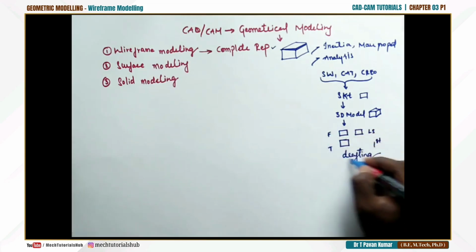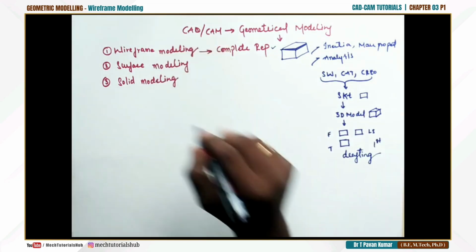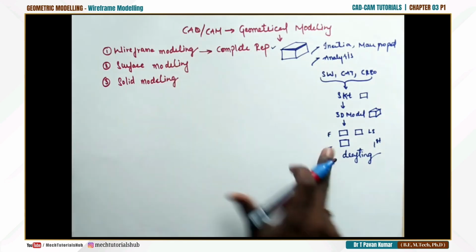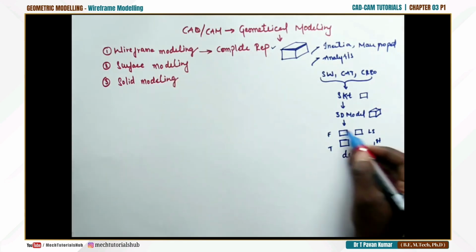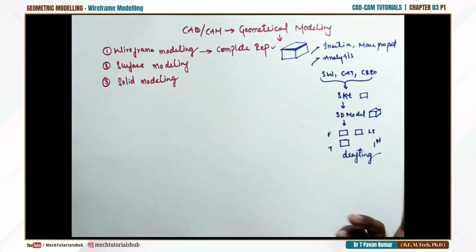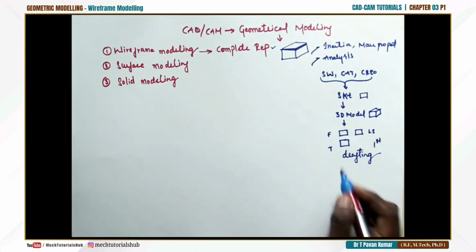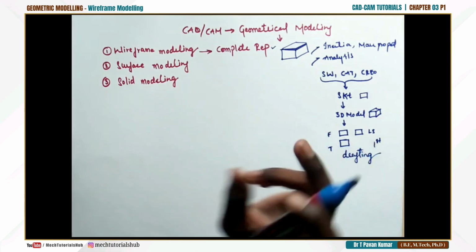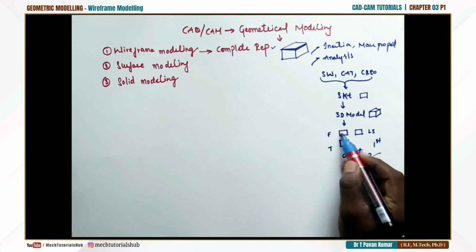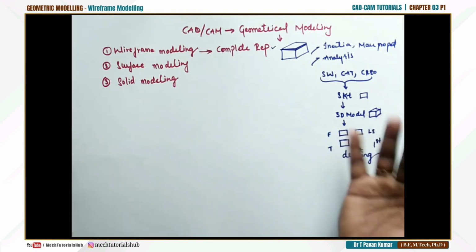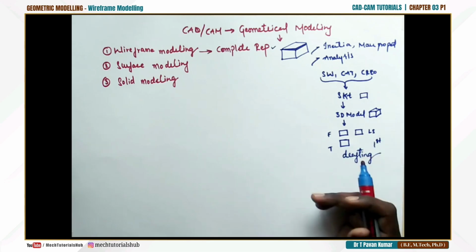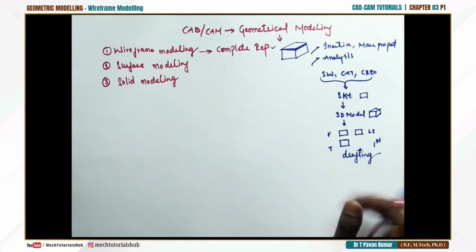Here the drafting is done initially, irrespective of a sketcher or a 3D model. They draw the front, top and side views just by taking an entity called a line or a rectangle. They simply go to the graphic window, take a line, start drawing a sketch of the box size and give dimensions for each individual view, followed by all the dimensions and whatever tolerances are required.